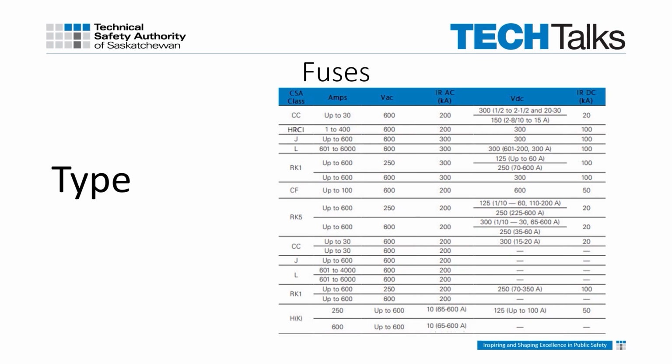There are several types or classes of fuse, each with distinct characteristics that make them specific for their intended use. Examples of fuse classes include, but are not limited to, HRC1 and HRC2, which are high rupture capacity fuses. Class H or K are general purpose, non-current limiting, non-time delay fuses with 10,000 amp interrupt rating as a minimum.